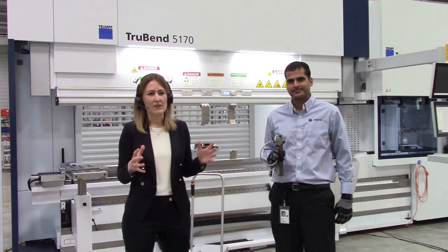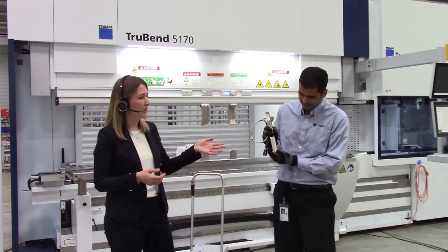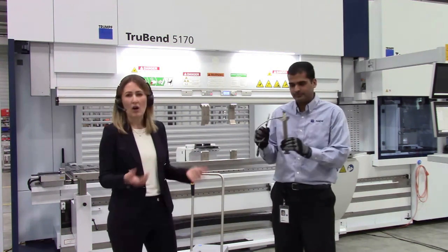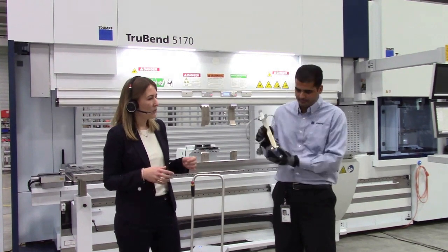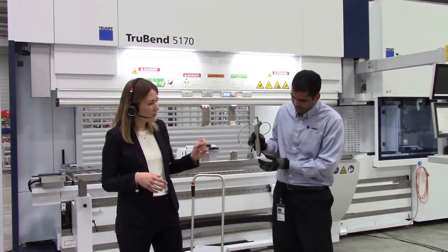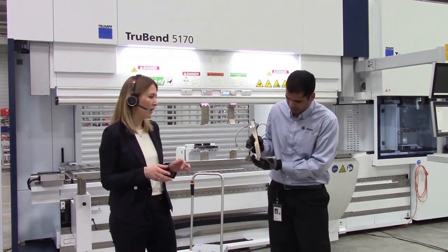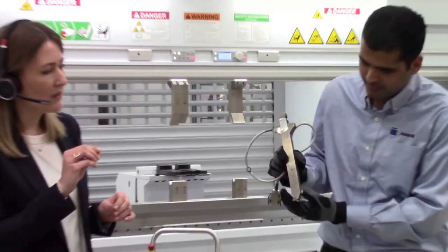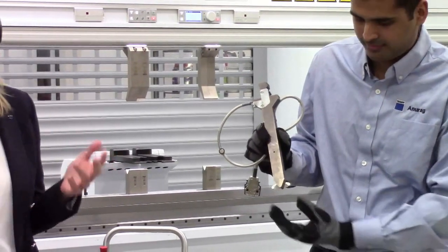And in the space of ACB, we have 2 different main areas, I would say. On the one side, we have the ACB hard tool, which we can see here. We have that both as a wired option in this case. We also have that as a wireless option. ACB hard tool works the following. We have 2 sensor discs here at the bottom, which will touch the inner radius of our part. And we are actually measuring the distance between the 2 sensor discs, or the centers of the 2 sensor discs, and that is how we calculate the angle.